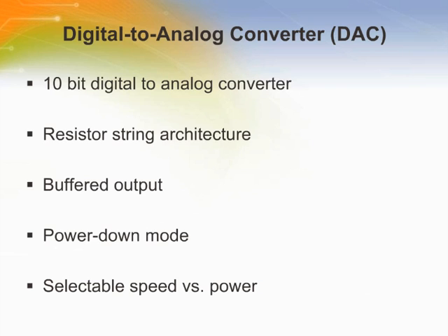This read-write register includes the digital value to be converted to analog and a bit that trades off performance versus power. Bits 5 to 0 are reserved for future, higher resolution digital to analog converters.